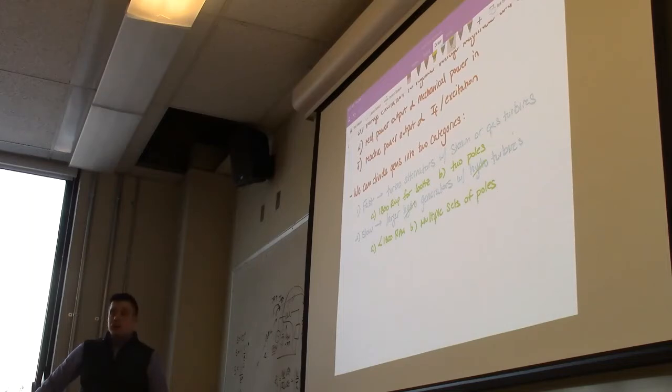Whereas for a hydro, they don't use a gearbox. They don't use any mechanical method in order to increase the rotational frequency. And that has to do with the fact that, at least for the hydro, it's a controllable constant slow frequency, whereas for the wind, it's a variable low frequency.